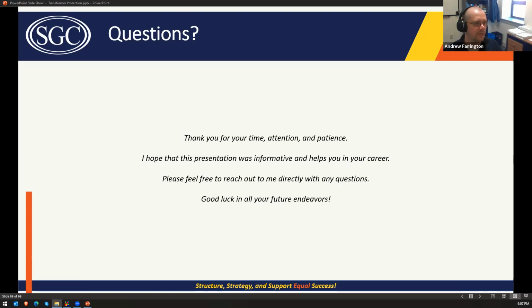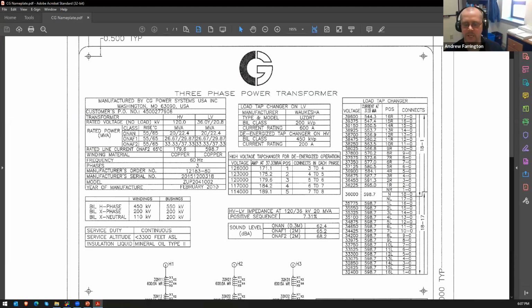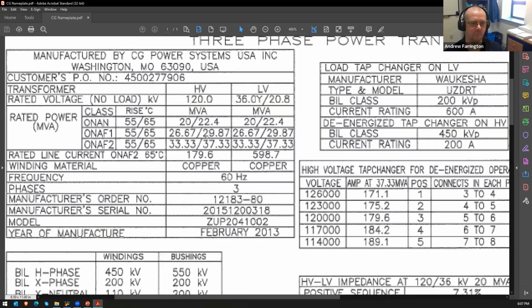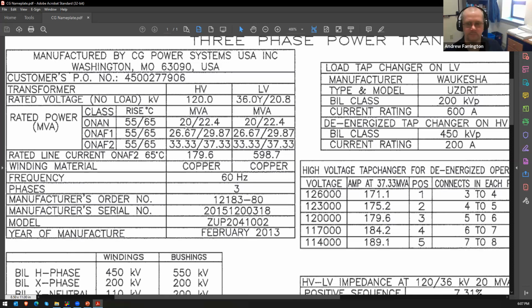The nameplate rating is like the generic term. The ONAN rating is a more specific term. So here's a transformer nameplate. Somebody says, you look at the nameplate rating, they're generally referring to the ONAN, but the nameplate has often more than one rating. Okay, so this one has 6 ratings actually.